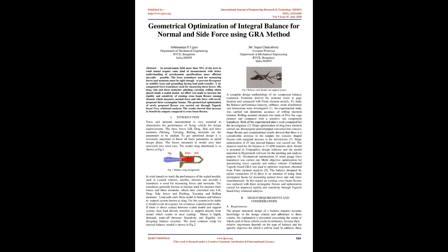Introduction. Force and moment measurement is very essential to characterize the performance of flying vehicle for design improvements. The 3 forces: lift, drag, side, and 3 moments: pitching, yawing, rolling moments are the parameters to be studied. To get optimized design, it is extremely important to know all these parameters at initial design phase. The forces measured in model axis later converted into wind axis. The model sting attachment is as shown in Fig.